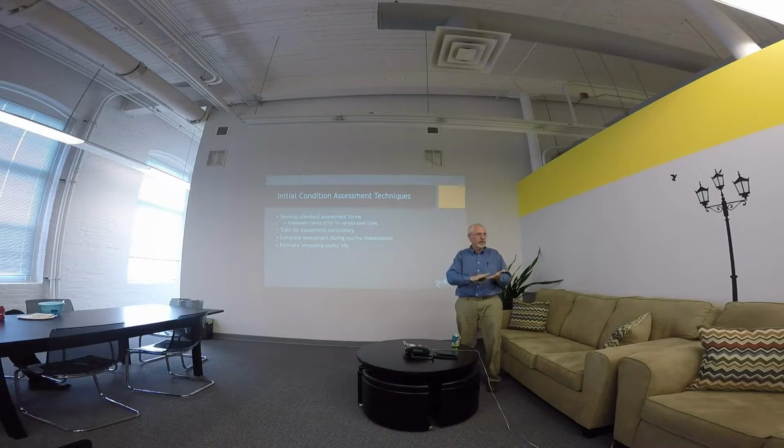Every time you touch the pipe, every time you go and do an oil change on the pump, and you hear the vibrations, do an analysis. Because you cannot have your assessment be something special all by itself, because you don't have time to do it. It has to be incorporated in your normal workflow so that people are collecting the data through the normal.